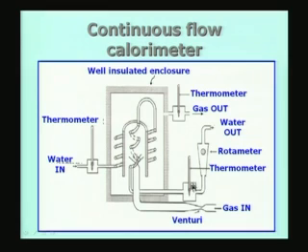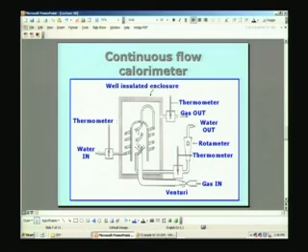So, all we have to do is to do an energy balance, which simply says the heat given up by the gas must be equal to the heat taken by the water, and by this balance we can find out what is the heat which is released by the combustion process. In fact, we can work out a very simple formula for that. So, let me go back to the board and work out a simple expression.